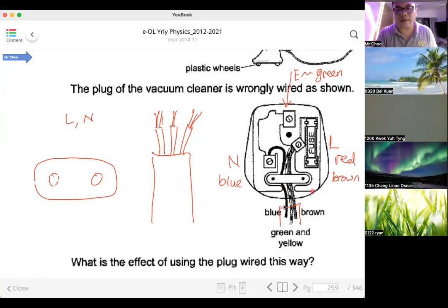If you want, you can tuck it even below this plastic thing. This outer insulator, you can tuck it just below this plastic thing. Okay, so everything is put in properly. You put the plastic over, press against this wire here. So this thing that I'm putting here is this slab here. Then you screw in these 2 screws to put all the wire in place. So actually it's not hard. Once that is done, you are ready to go.